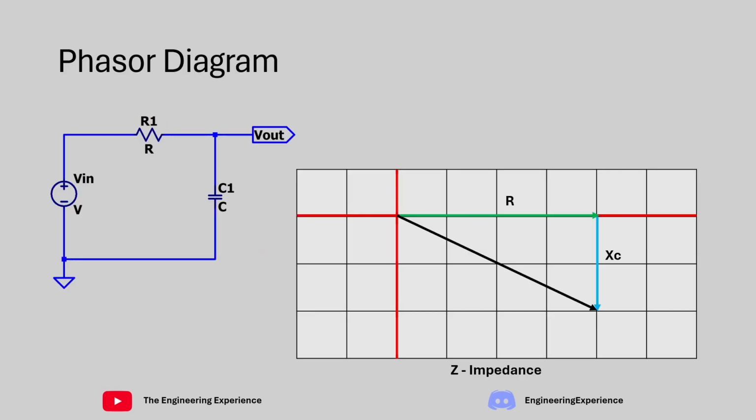First of all, a little bit on low-pass RC filters and phasor diagrams. We have covered both of these topics before, so I won't go through it in much detail. Essentially, a low-pass RC filter is where you have the capacitor in parallel with the load and the resistor in series with the load. This attenuates any high frequencies that the load will see, as the impedance of this capacitor is very low for high frequencies.